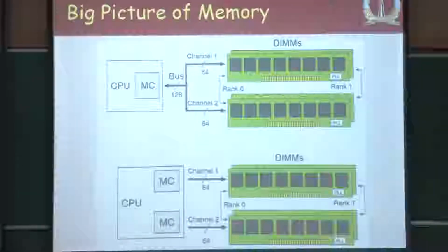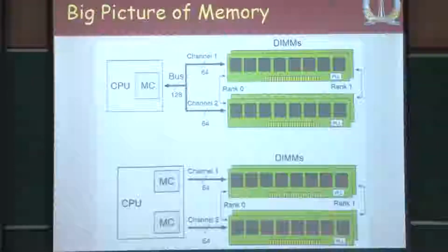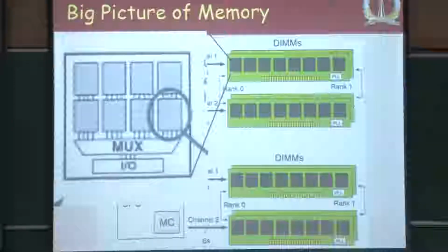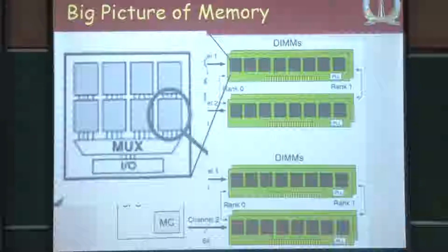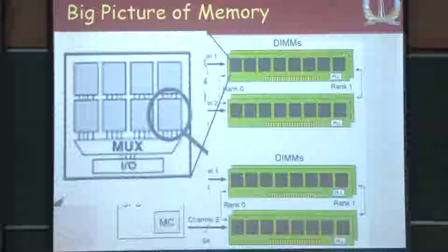We are going to see the organization of this memory in greater detail in this talk. So, again you could see that the DIMMs themselves could have rank 0, rank 1 and so on and so forth. Either a single DIMM can have 2 ranks, or multiple DIMMs can actually go into multiple ranks. So, each one of this chip that you see in your DIMM is basically what is called a device, and that device itself contains multiple banks.